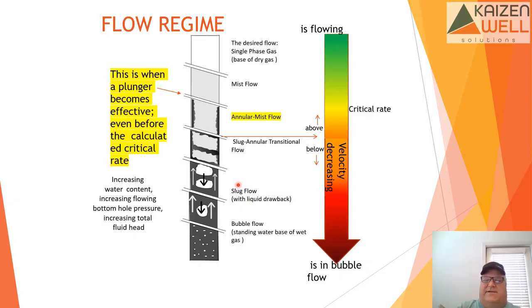And of course, if you were looking at a chart or your SCADA, you would see these big spikes in gas, and then a drop off, and then it might sit near very little flow, and then a big spike, and then very little flow, and that's pretty typical of slug flow with liquid drawback. And it's pretty interesting. Once you get these slugs of liquid falling, it's quite hard to stop them from falling and turn around. So you actually get this real buildup of energy that has to break through that liquid dropping, and then so you get a lot of these peaks and valleys.